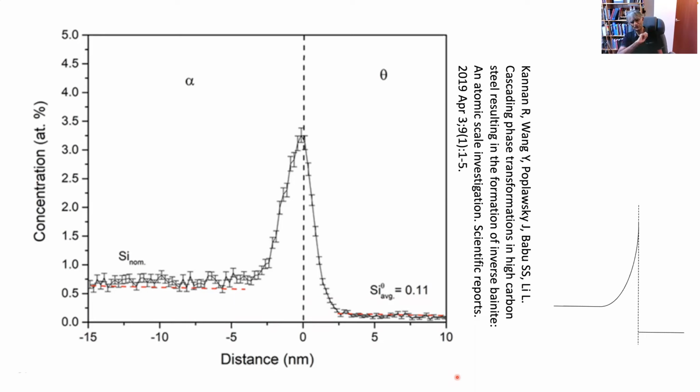But look at this concentration profile, for example, which was published in one of the Nature journals. It makes no sense at all, okay? So this is identified as the position of the interface. The compositions of the two phases at the interface are exactly identical, which goes against chemical potential being the governing criterion. And you have these gradients in both the phases. It makes no sense whatsoever, okay? The width of this is many, many nanometers. So I think there is a real problem of spatial resolution.